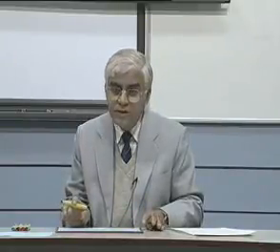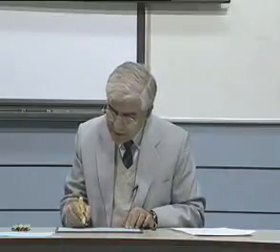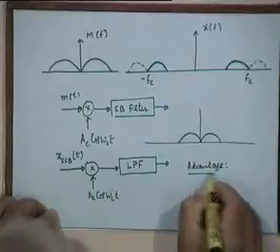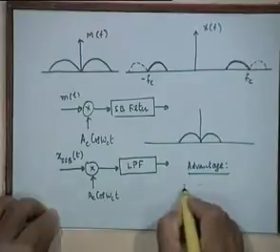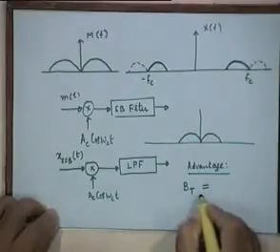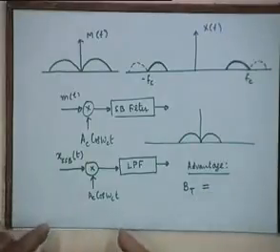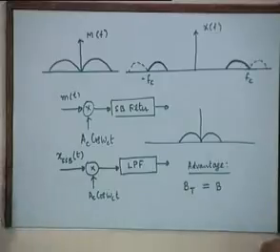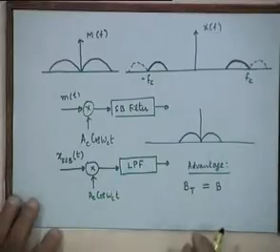Now, so far so good, but before I come to that, what are the advantages that we mentioned of doing this? The main advantage is power bandwidth efficiency. Your transmission bandwidth B_T is now not equal to 2B, which was the case for the two previous modulations we discussed, but simply equal to B. So, in the same bandwidth now you can transmit twice as many messages. You can transmit two messages in the same bandwidth rather than in the 2B around f_c rather than a single message, okay. That is the main advantage.